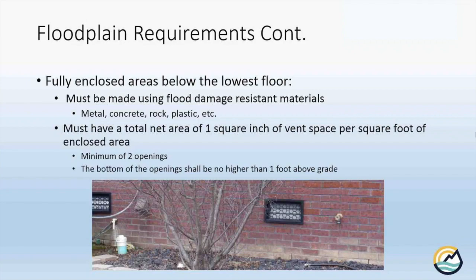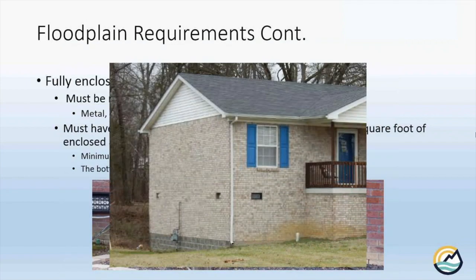Here's a great example of what I mean. This is a house that has a crawl space underneath, but the flood vents there in that back corner, where water would hit it first, are more than 7 feet in the air. So you have to have 7 feet of water pushing on that foundation before those vents do anything. So those vents really aren't helping you any.